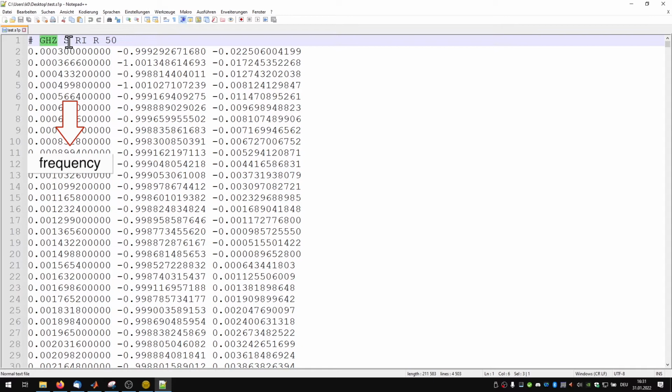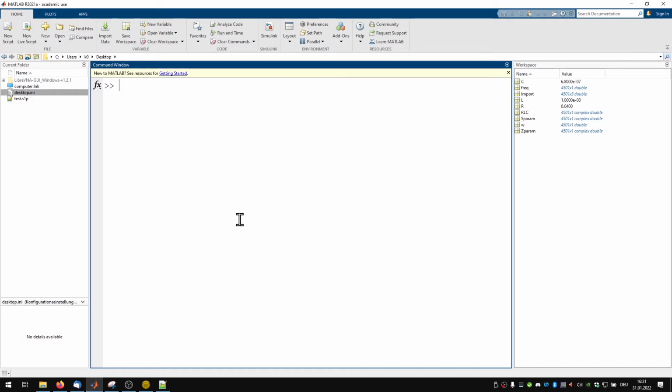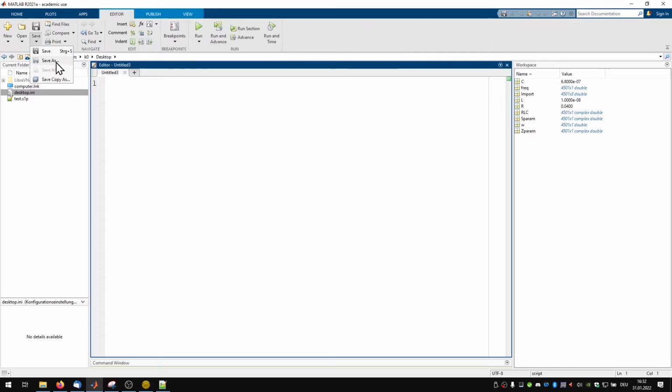We have stored S parameters, but we can easily convert them into the familiar Z parameters. Columns 2 and 3 are linked and indicate real and imaginary part of the measuring point in a 50 ohm system. Many simulation programs such as Keysight ADS can natively handle Touchstone files, but also with MATLAB or Python, the import is quite simple. Let's just quickly write ourselves such a script.